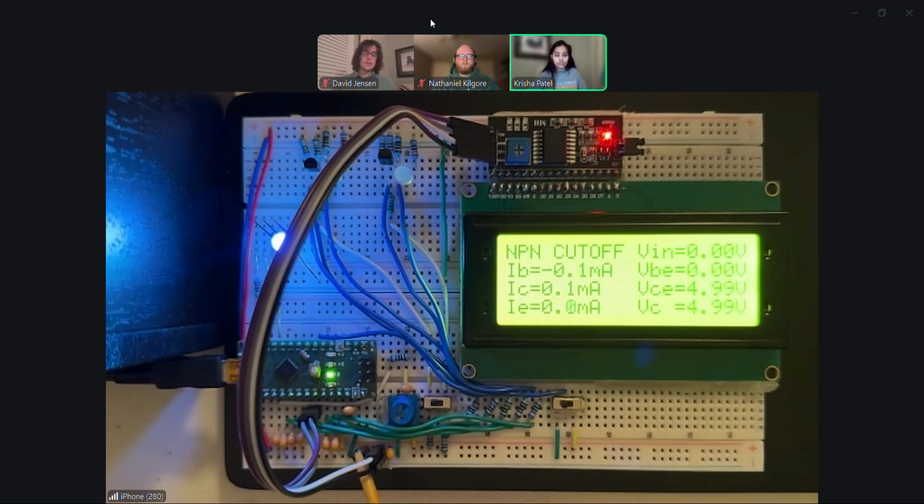We use capacitors here on our power rail for decoupling purposes to help filter any noise and just smooth any transients in our signals. Moving along here, we pick up power and ground for our potentiometer, and that is output into 2 places. One of them is here, and it goes through this resistor and back into an analog input here, and that allows us to directly measure our input voltage.